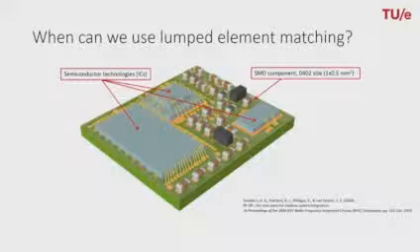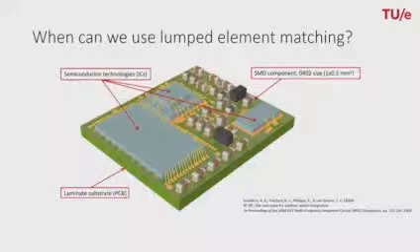These integrated circuits are, in this case, wire bonded to a substrate, which is the carrier of this system in package. In this particular application, Bluetooth, which operates at 2.5 gigahertz, the wavelength is 12 centimeters, which is much larger than the size of the SMD components, because that was only 1 millimeter.